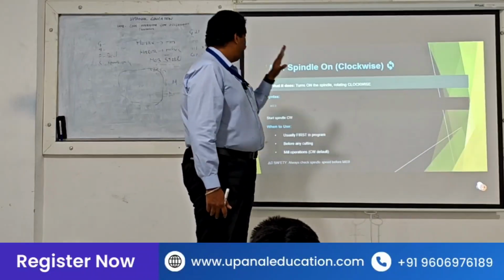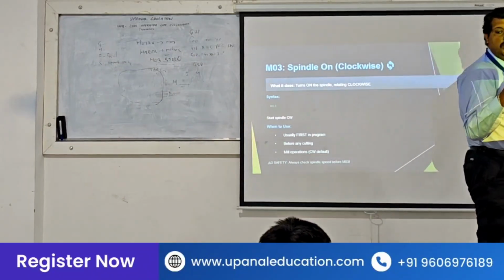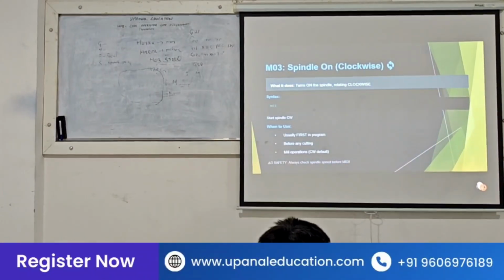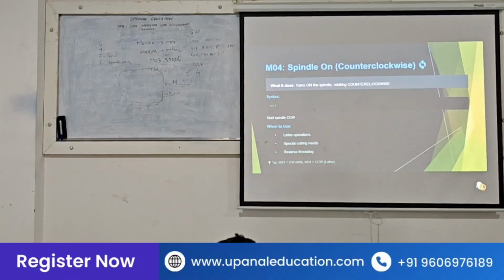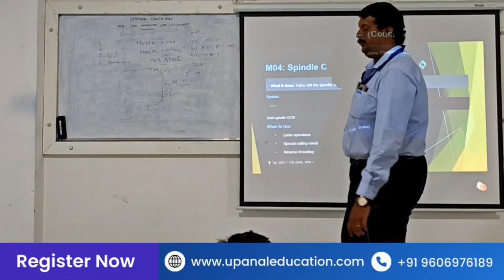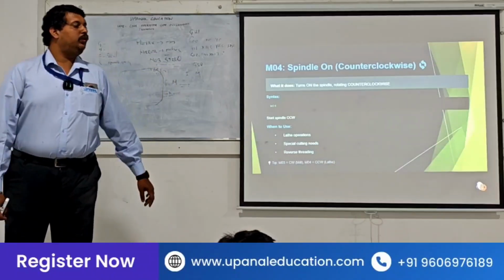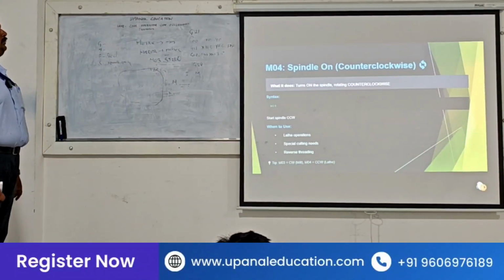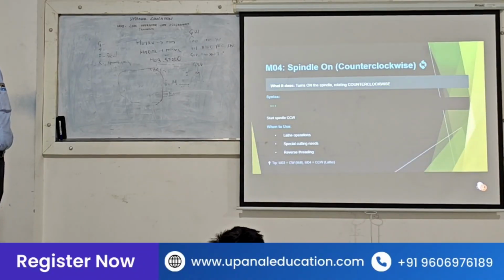So M03 is spindle on in the clockwise direction. Now, if you want to rotate in the counterclockwise direction, the opposite side, what do we do? It is M04. M04 is spindle on in the counterclockwise direction. Why do we do this, left side and right side? Why do we have counterclockwise and clockwise?